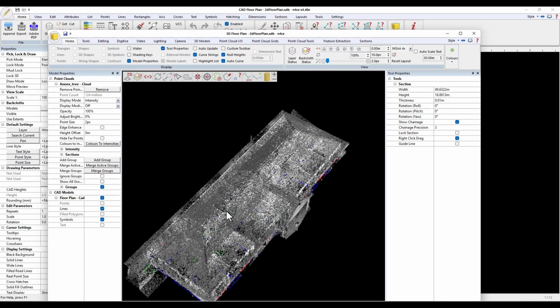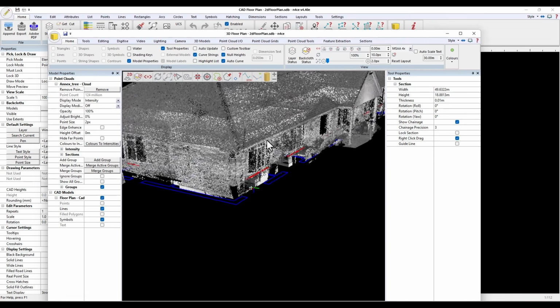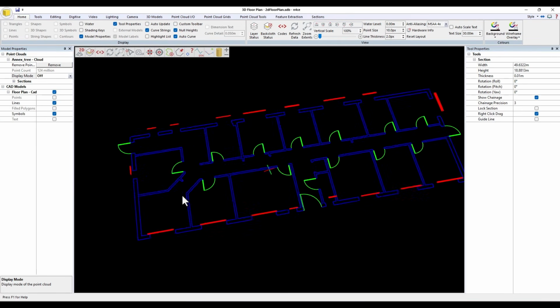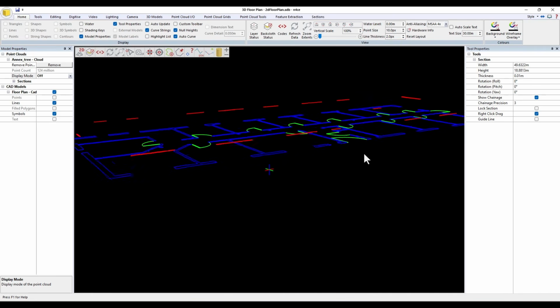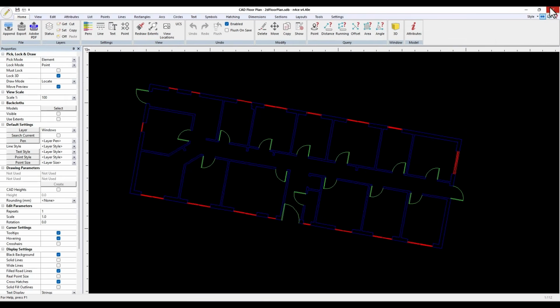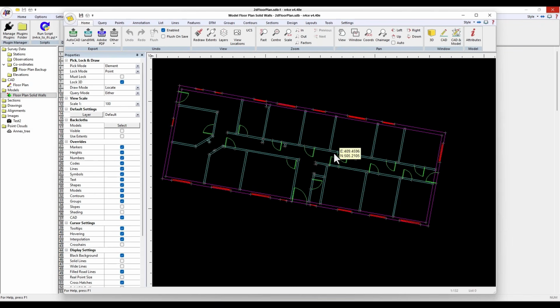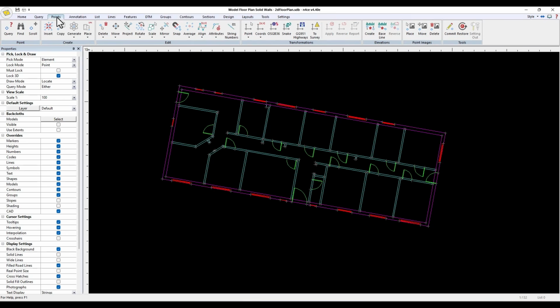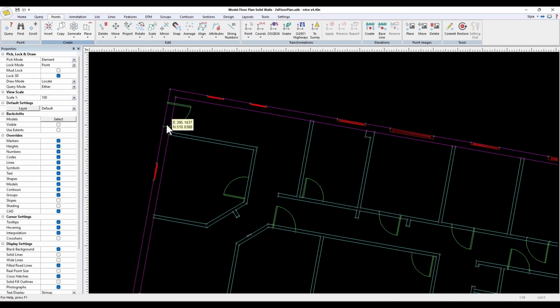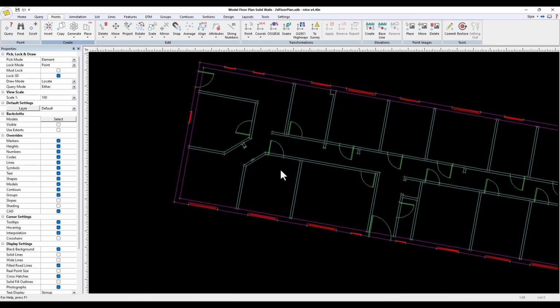So this data here is drawn all at the right level, but it's essentially a 2D kind of CAD plan, or pseudo 2D, okay, with these entities, these doors and window openings, etc., all at the right height. So what I did first of all was I took this data and I used the n4ce tool where we can generate point data from CAD information. So I generated it from elements, because when I do from elements, it'll do it from symbols and lines at the same time. So we have obviously symbols for the doors, symbols for the windows, and just basic line work for the walls.